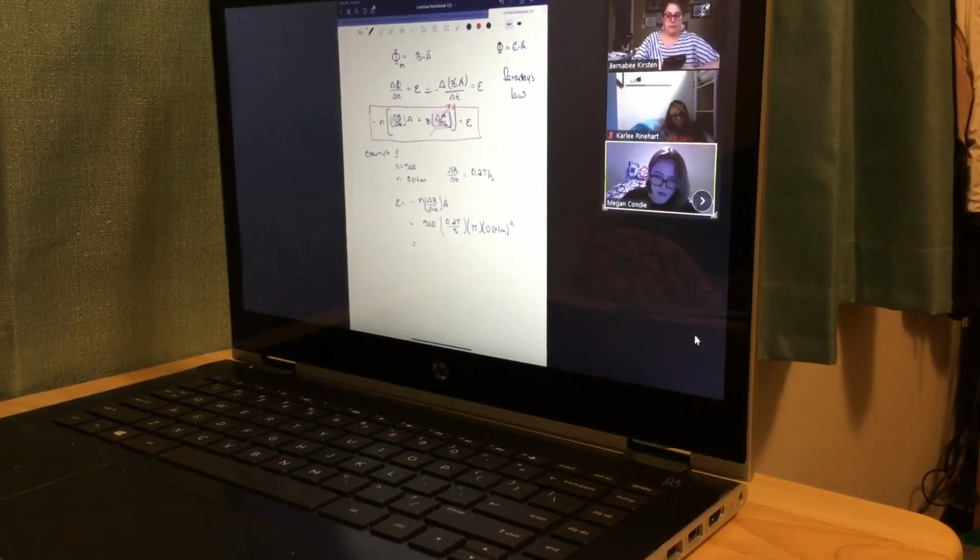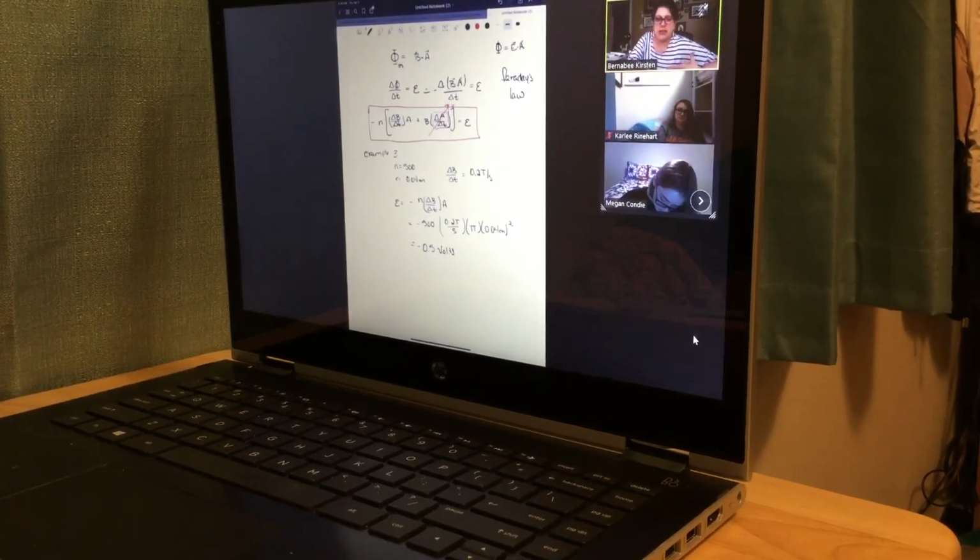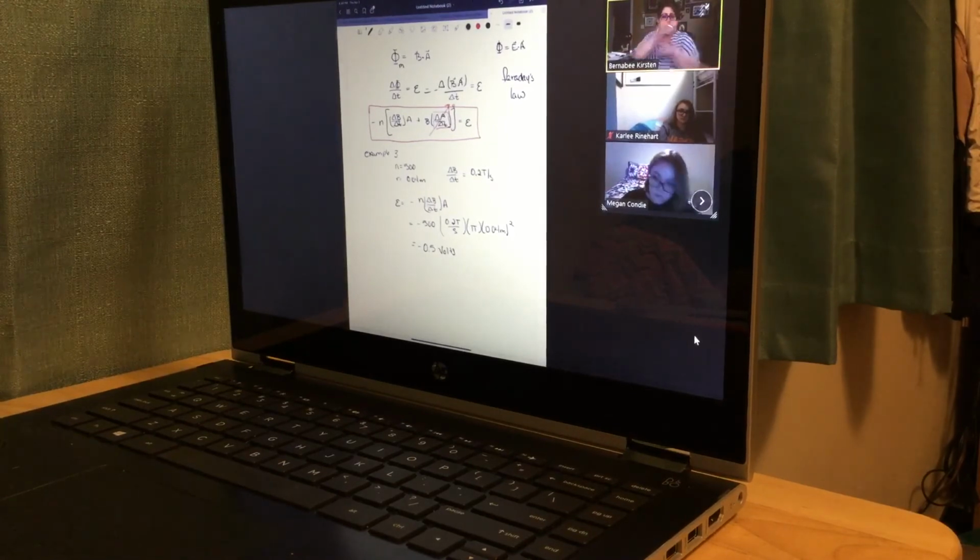You have a negative in there. Yeah, we're going to talk about him in a sec. So a couple things about that negative. It really is just there for convention, and a negative voltage doesn't really mean a whole lot. I mean, turn your voltmeter around, connect the leads opposite, and you'll get a positive voltage.